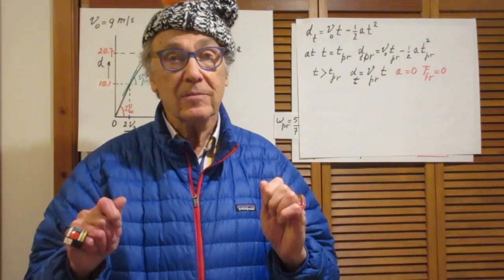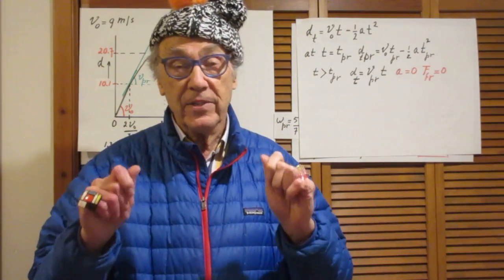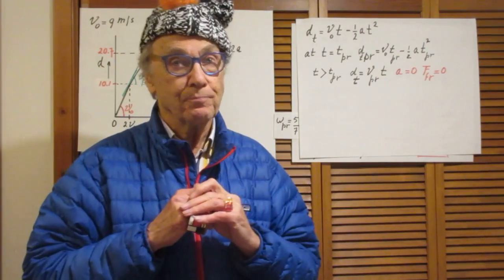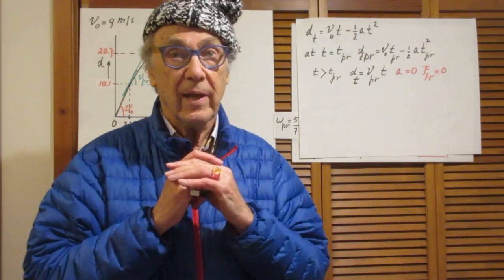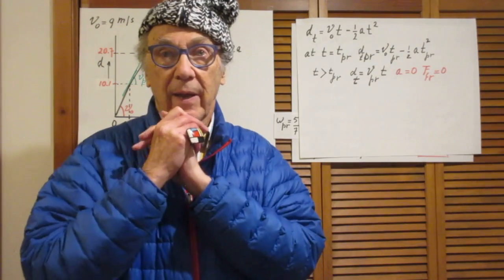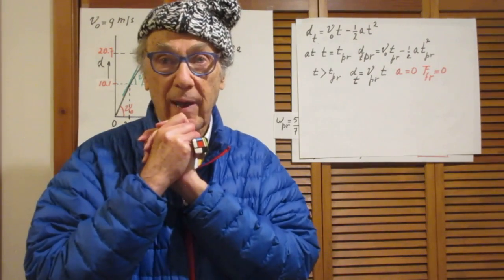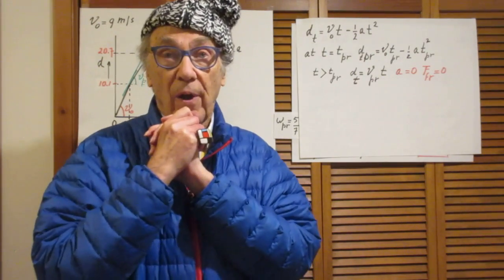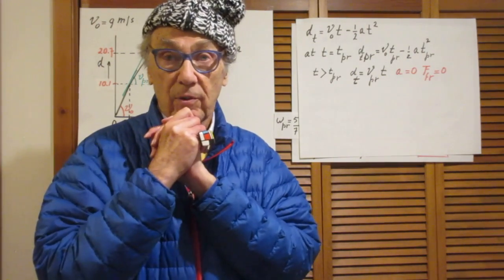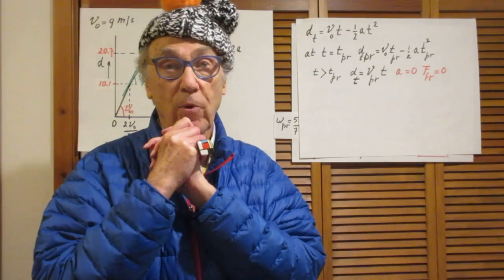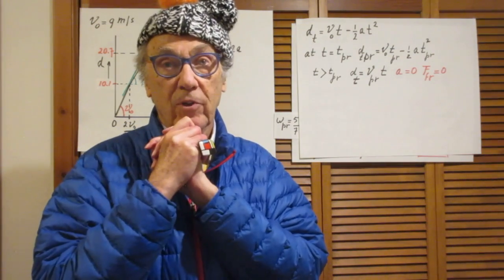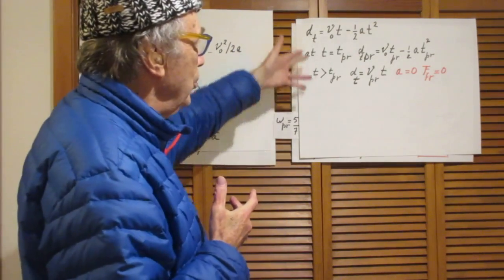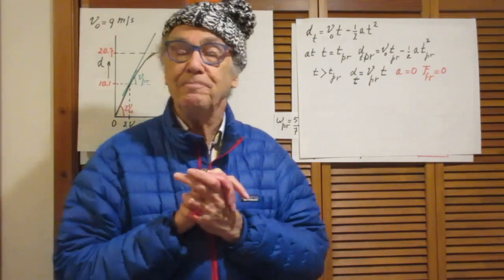In the beginning, as long as there is slip, as long as the disk is skidding, omega will increase and the speed will decrease. There comes a time that V equals omega R, the friction goes to zero, omega will no longer change, no energy will be lost anymore, and V will no longer change. That's very, very basic. And you see that also in a beautiful way in this equation.